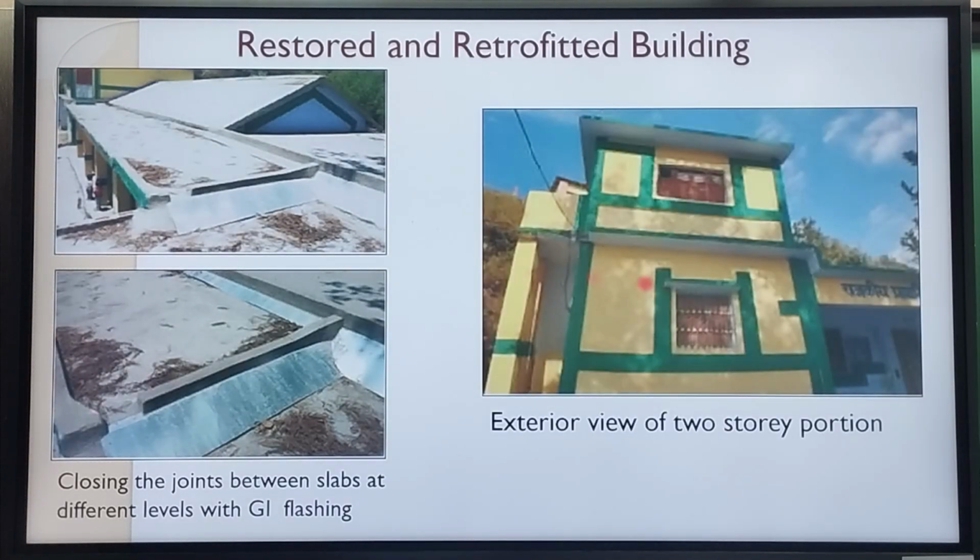See here, actually, from the tin roof on this passage slab, there was no problem of leakage because there was adequate overhang over that. Okay, the tin came out almost 9 inches, so there was no problem, and the water basically drained down from the slab. But here, between this slab and this slab, there is a gap of about 4 inches. So this is where we had to provide the tin.